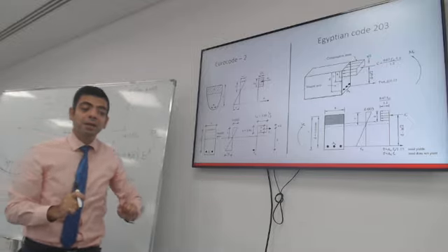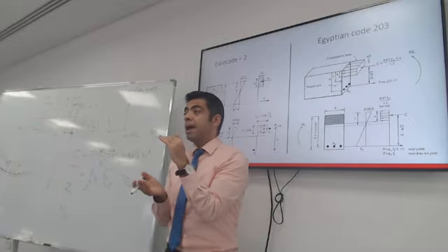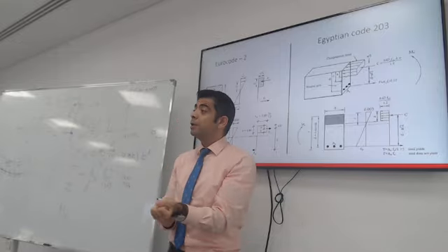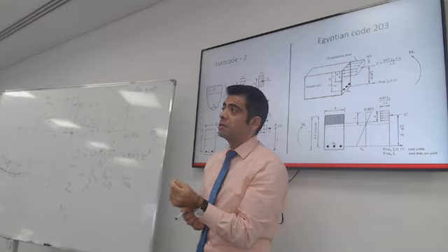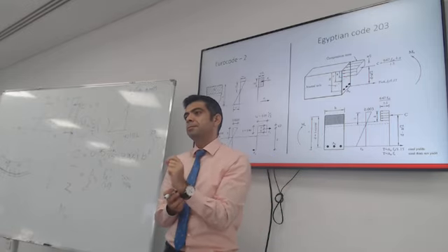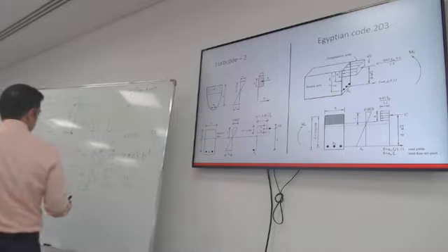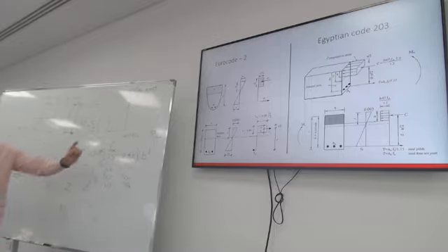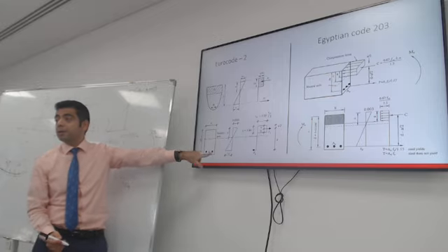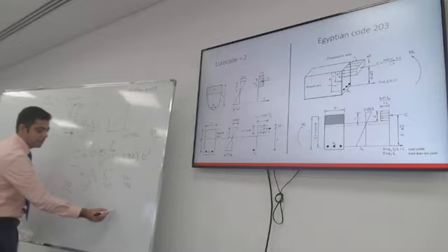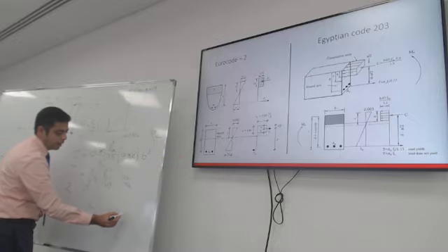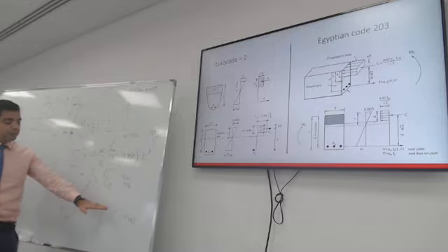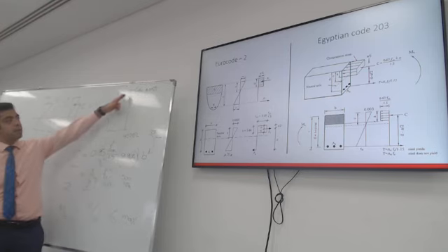And what I mean by control is that you can have too big an X, so that concrete will fail first. I already mentioned that you want to avoid compression failure. So how do you avoid compression failure? You make sure that the ratio between X and the depth D, which is from the top fibers to the center line of the reinforcement, is less than or equal to a maximum number. This maximum number we calculate from the strain distribution.